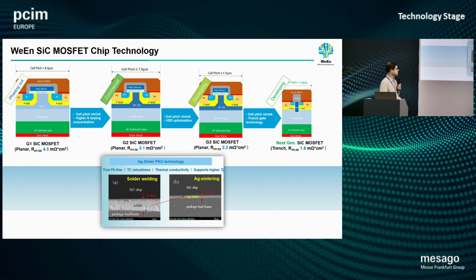But not only on the silicon, we're also working a little bit at the packaging level. You can see here that silicon devices were typically welded to the chip, and you can see the layer of solder. And this layer was okay for silicon because you only really go to 175 degrees, 150 degrees. But with silicon carbide, actually the chip can withstand temperatures much higher than that. It can go up to 200 degrees. And so what we're doing is we're leveraging the use of sintering to be able to increase those temperatures and really improve the power density of the converters.